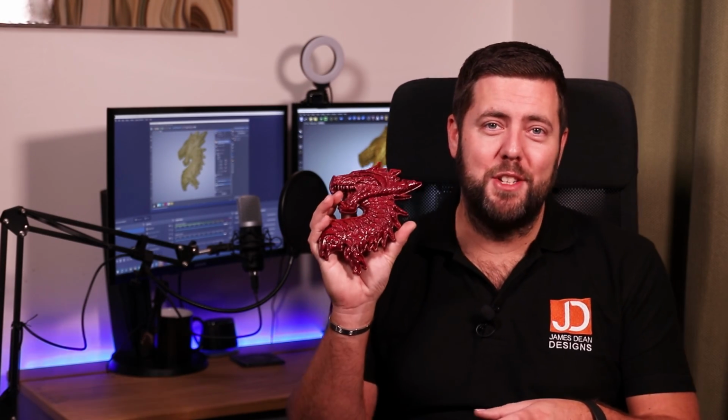So we imported a 3D model, we manipulated it a bit and generated all the toolpaths to move on and get it cut out. Now earlier on in the video I spoke about the 3D relief library that's inbuilt. This works in exactly the same way. Once you drag those in and paste them down to your model, you create the toolpaths just as we did in today's episode. So it's very easy once you get stuck into it.